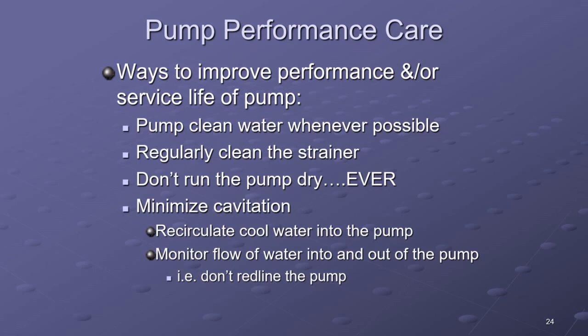Don't redline your pump. Pumps are completely designed to run at their maximum RPM, and there's nothing wrong with that. You just need to make sure you're taking care of the power plant that's running it when you're doing it. If you're running those little 3-cylinder diesel motors at 3,000 RPMs, you're going to want to ease them back down and let them cool off before you just shut it down. Otherwise, your pump can push a lot of water. It can make a lot of pressure. You've got to balance these pieces.